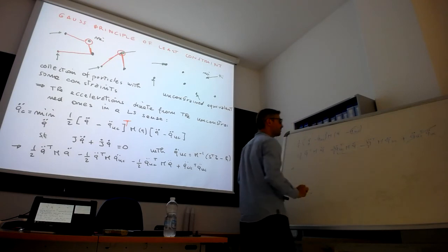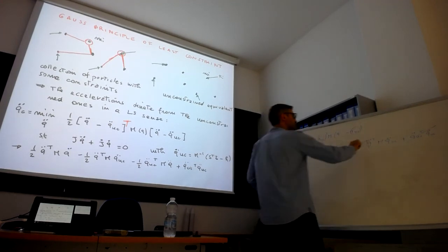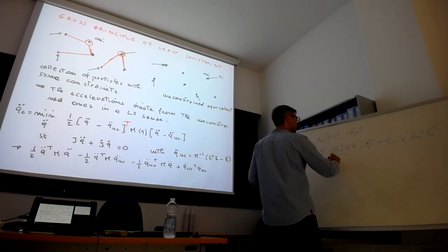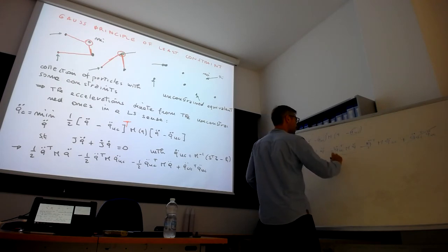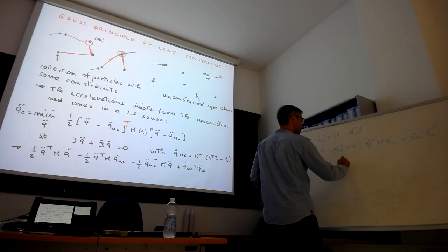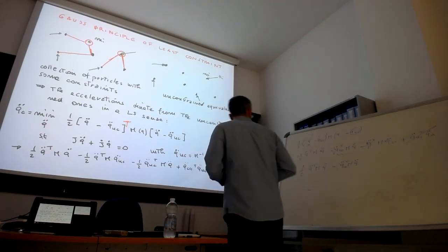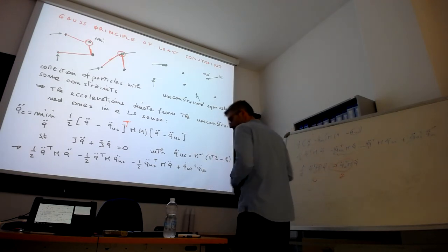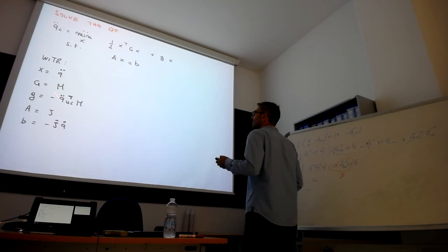We can see that this is a scalar. This is a quadratic form, you get a scalar, but you also get a scalar from here. In a scalar, the transpose is equal to itself. So if we transpose this, we can sum these two terms because they are the same, and we get this expression: minus the sum of these two becomes 1, q dot dot transpose M q dot dot unconstrained. So whenever you call your QP solver, you put this matrix in, and this G is the linear term. And that's it.